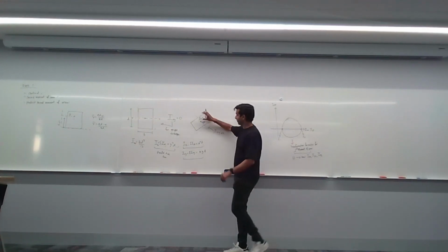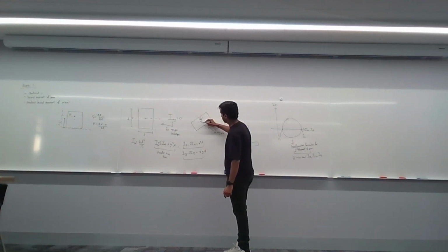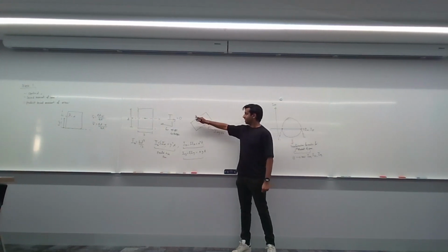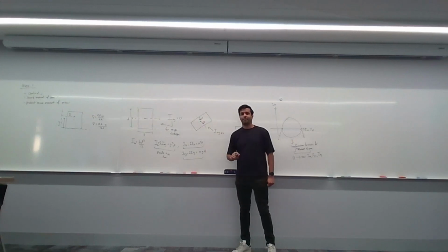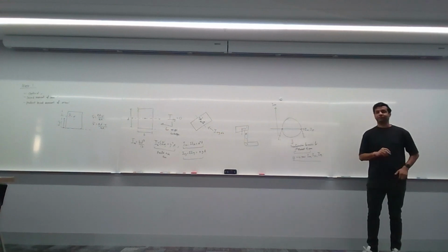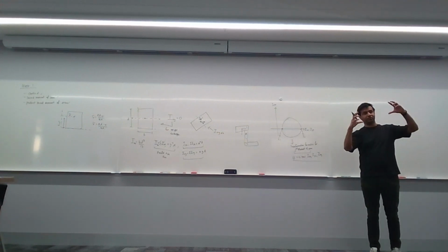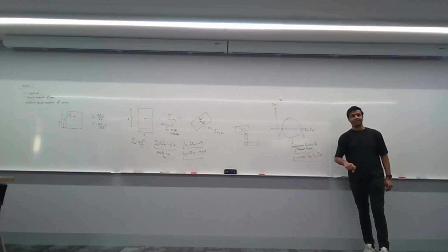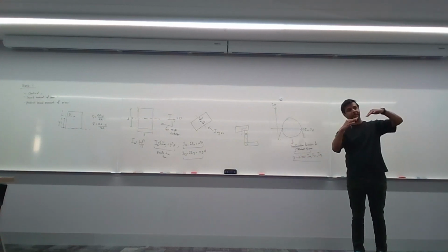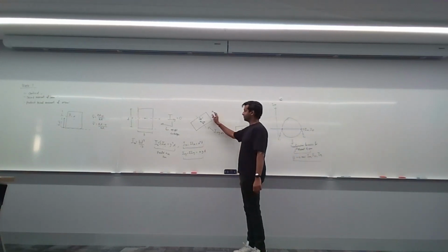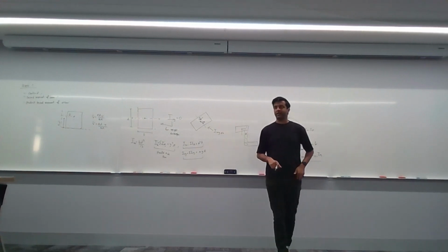Or I suppose the other way around, by this angle theta. Starting from this line, I need to rotate it this way. And I can drop in my transformation formulas to calculate the new Ixy, using the theta. So starting from 0, you rotate and you get the new Ixy value. That's how you will calculate Ixy for shapes that are inclined, okay?